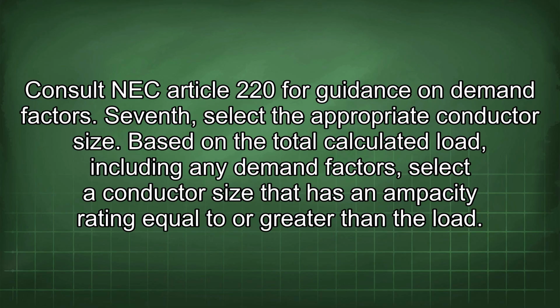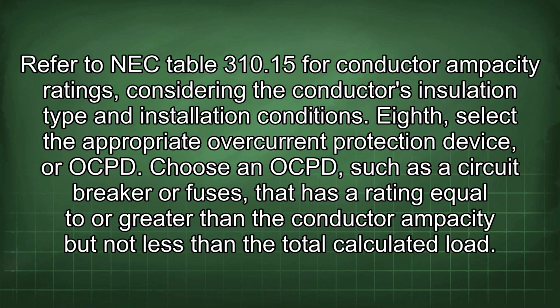Seventh, select the appropriate conductor size. Based on the total calculated load, including any demand factors, select a conductor size that has an ampacity rating equal to or greater than the load. Refer to NEC Table 310.15 for conductor ampacity ratings considering the conductor's insulation type and installation conditions.